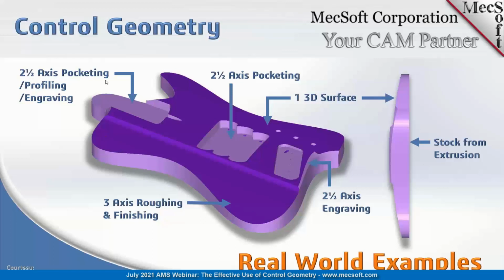We have some pocketing, profiling, and engraving going on here in the neck area where the neck attaches to the body. I mentioned previously that users use engraving to control exactly where the tool goes, and this is one example. And we got 2.5 axis pocketing going on, more pocketing here. We got 2.5 axis engraving where we got some contoured edges here, and there's another contoured edge up here. You can see it a little bit. And then we have 3-axis roughing and finishing. So let's move on to the next example.